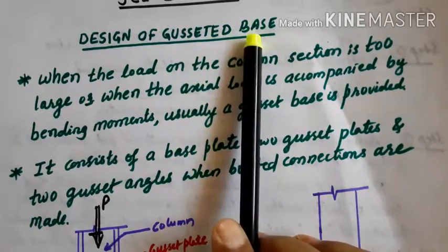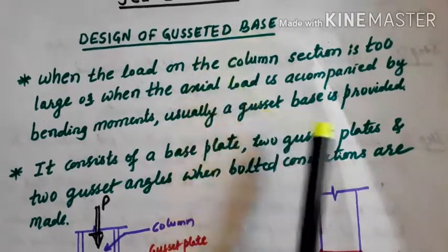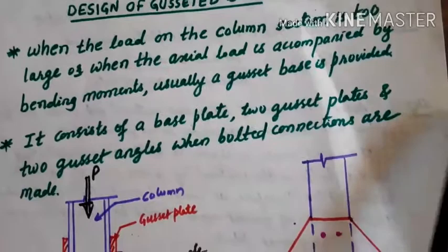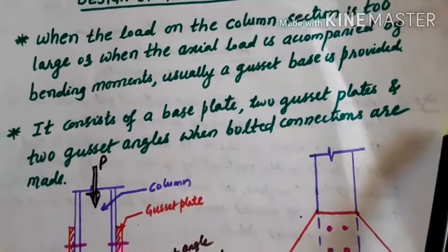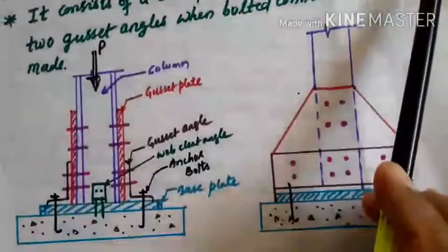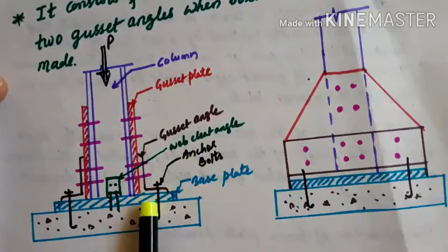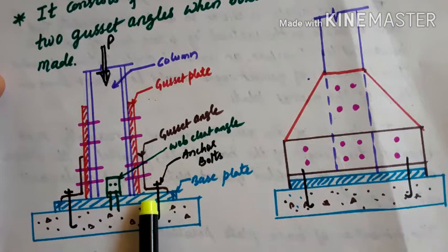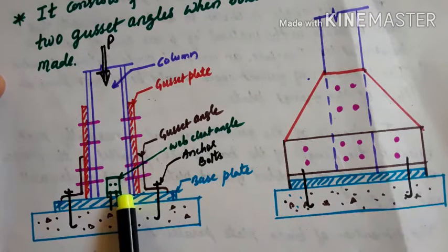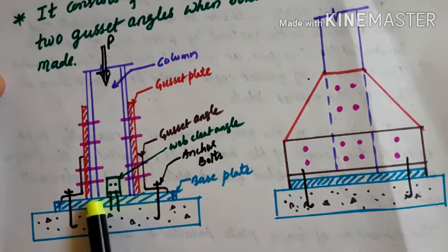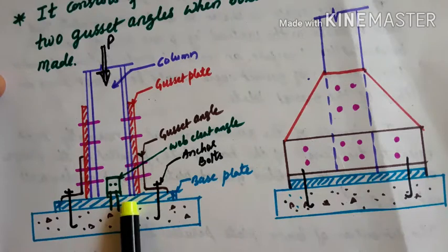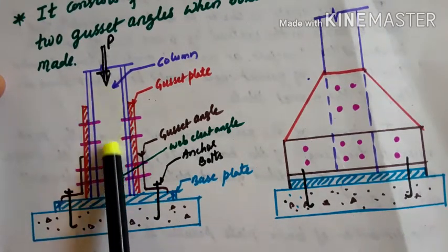As I explained earlier, in a simple slab base, a simple base plate will be provided underneath the column, like this, and that base plate is welded with the machined edge column. That plate is used only to take the lighter side load coming on the column.